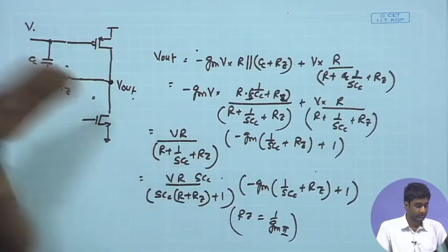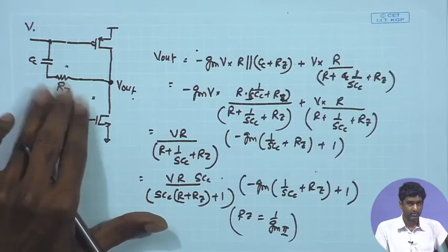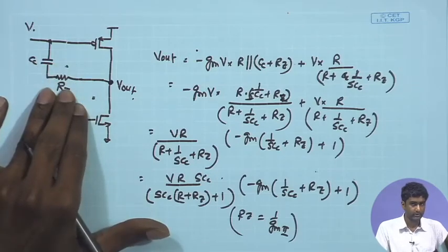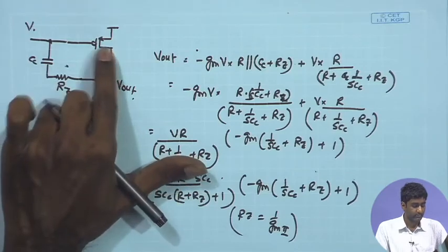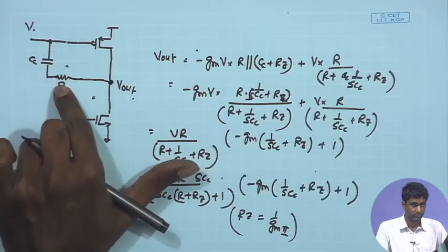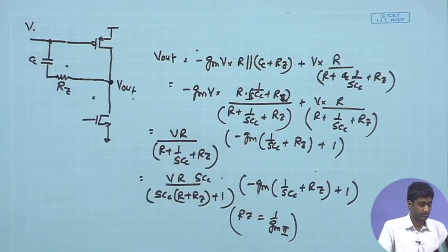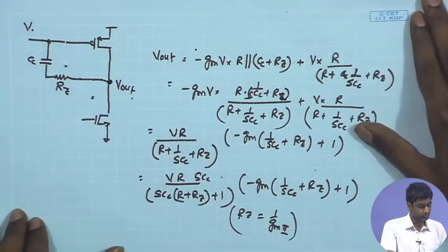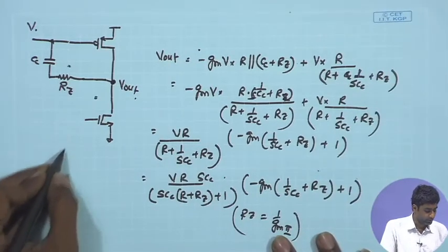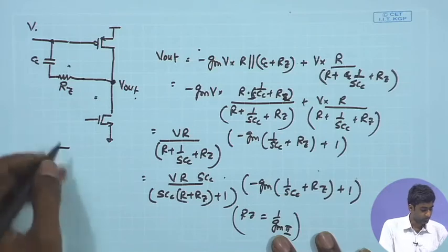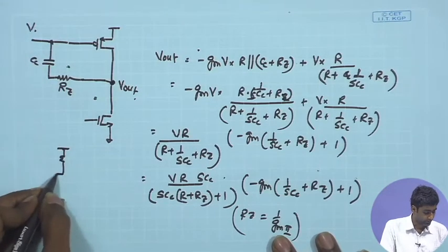So, that incorporates a current reference circuit that we have not implemented yet in our design. We will very briefly visit that and try to see how it can help us in establishing a GM which is controlled by the RZ or is proportional to the RZ, so that the cancellation can be much more robust. So, to do that, the scheme employed is that we use a PMOS current reference.